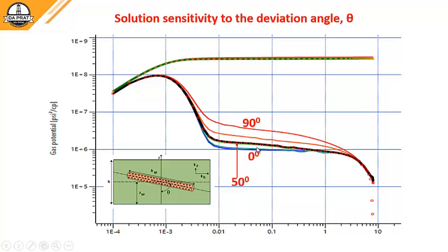But if it is more like 50, like the one we have, you can see the importance of recognizing that this is not radial flow in the formation. Radial flow is over here. If you compute radial flow here, you end up with a value of permeability less than the one that it should be.